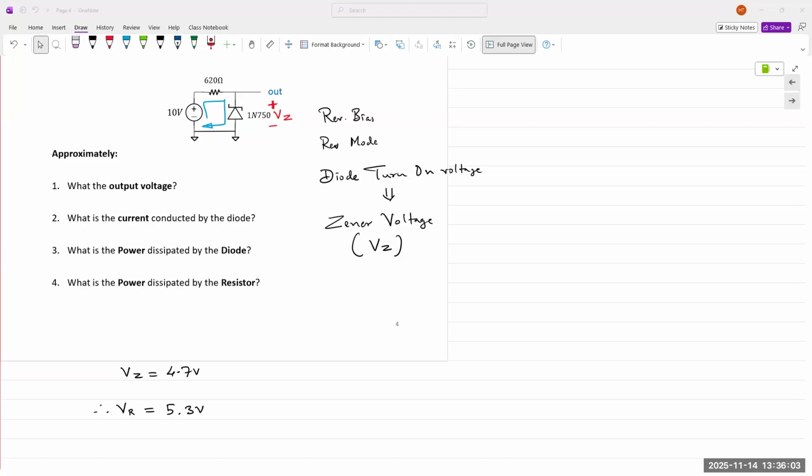That is correct. So the question being asked, or more of a statement or clarification, is that the Zener diode sinks more current to itself, but it keeps the voltage constant. The rest of the voltage drops across the resistor. Right? Is that the question? Yeah, that is correct, that's how it works. And then, of course, as you stated, one part of the statement was until it reaches a certain limit, which is what I'm going to talk about next, if there are no other questions.